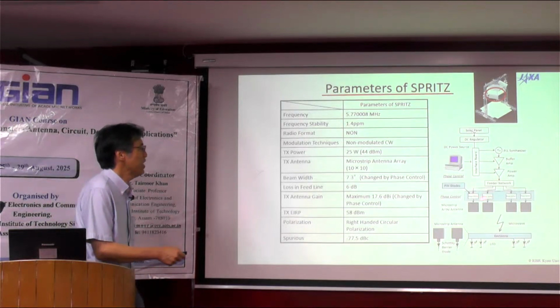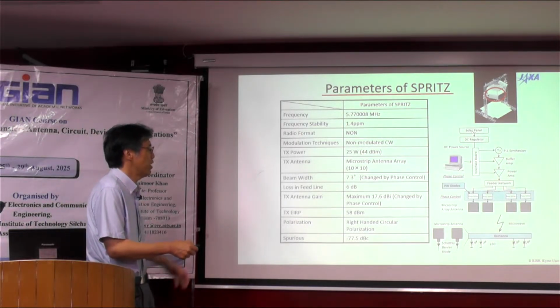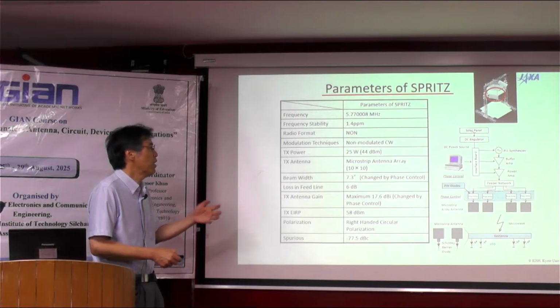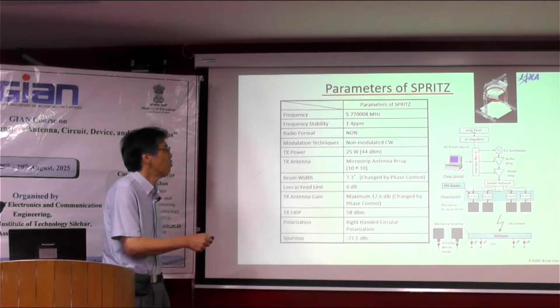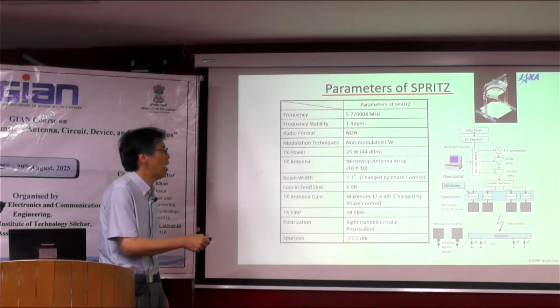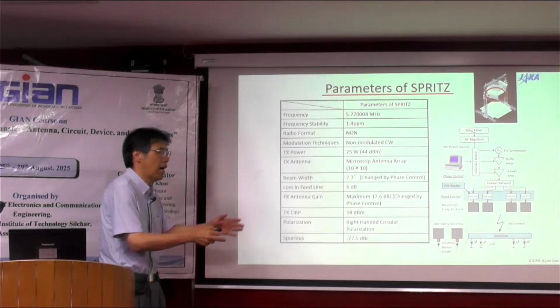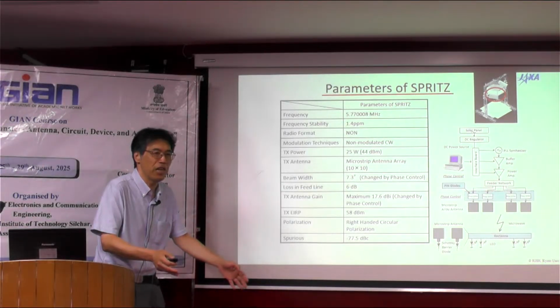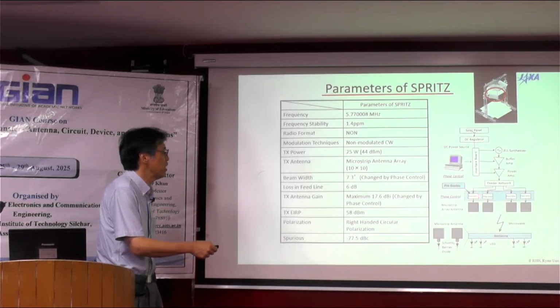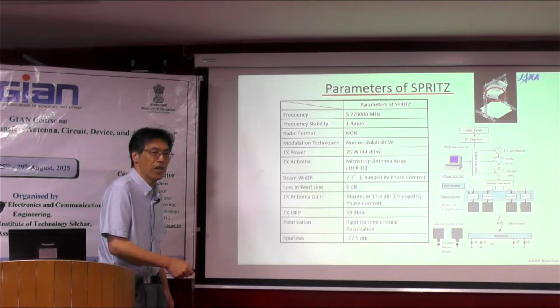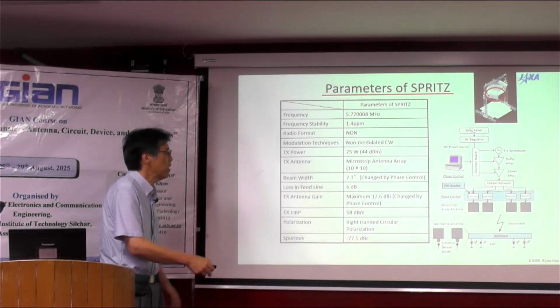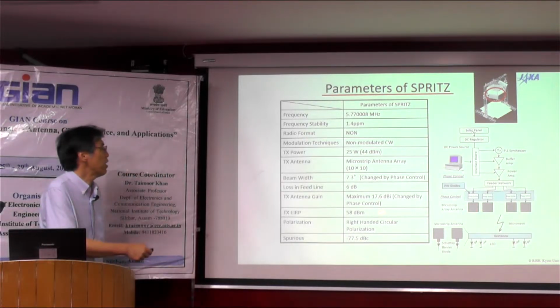we adopted another phased array diagram. We add only one very high power amplifier. And after the high power amplifier, we install the power divider, or feeding network, into 100 phase shifters and antennas. We install the phase shifter only after the power divider. And at last, from this antenna, we control the beam direction. And the parameters are there.